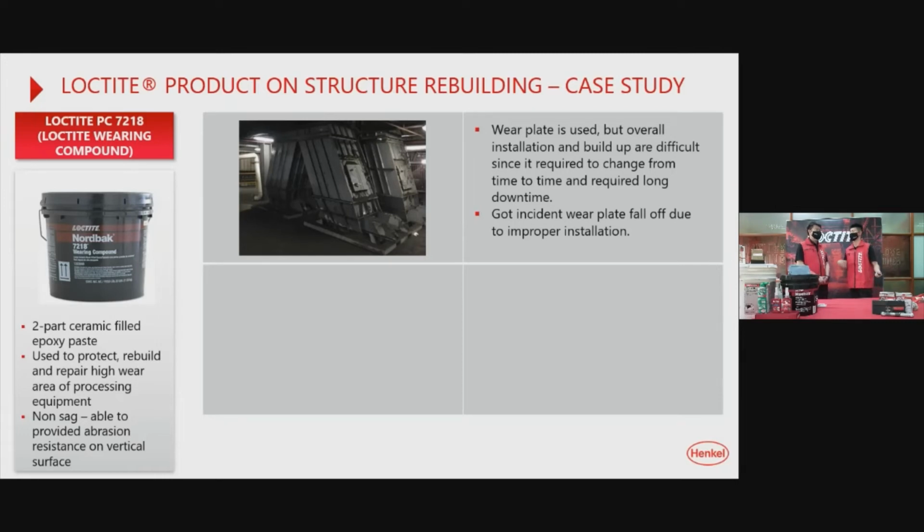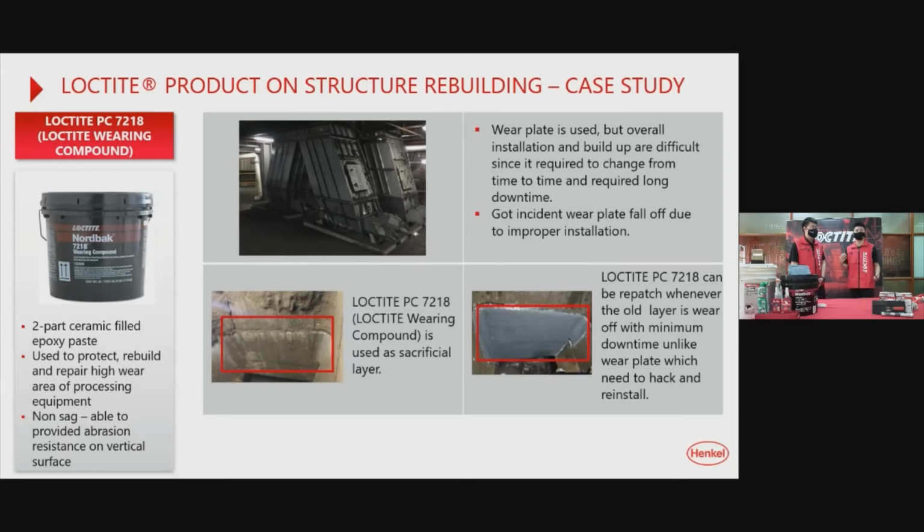So that's why this has already caused the damage. Then along the time we know about this issue, we introduce them to use this wearing compound to do some protections or to act as a sacrificial layer for their chutes. And up until today, no issue, because we actually help them to eliminate this plate falling issues.